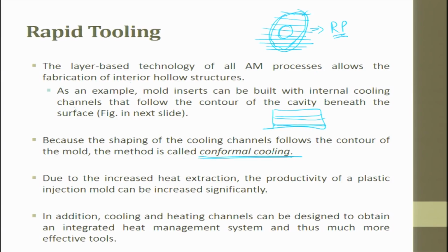The cooling channels follow the contour, so it is called conformal cooling. Due to the increase in heat extraction, the productivity of a plastic injection mold can be increased significantly. When you start making the channels in the mold, the efficiency of the process goes high. In addition, cooling and heating channels can be designed to obtain an integrated heat management system.